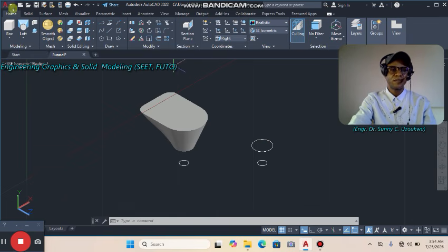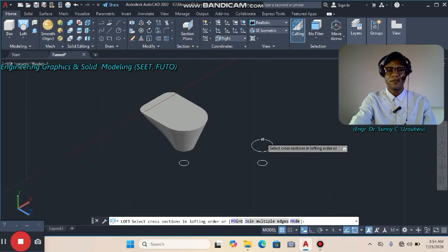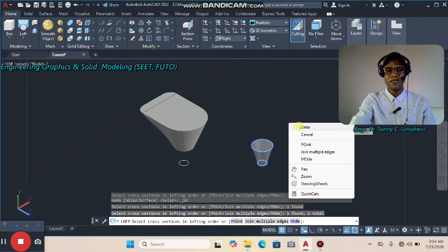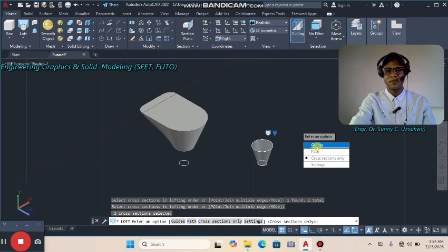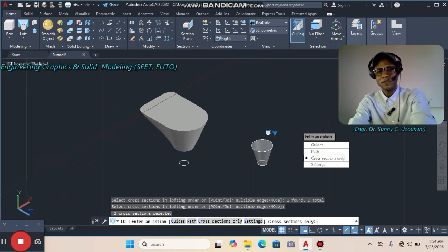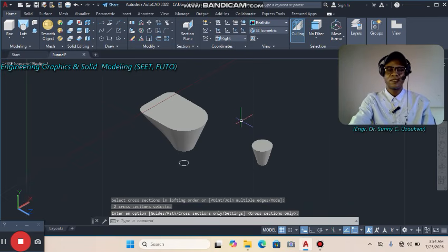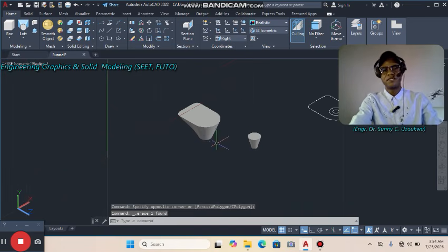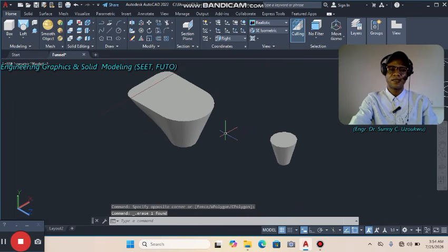So how do you go about that? Take up lift, click on it. You don't need to jump because it's already a single member, and that is that. Okay, it's a cross section. Enter. That's that. Good. Now it's ready to join the two elements together. I can delete this. How do I join it together? Now I can zoom it big,